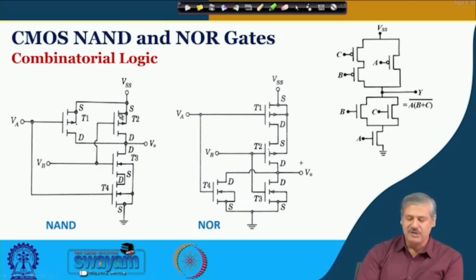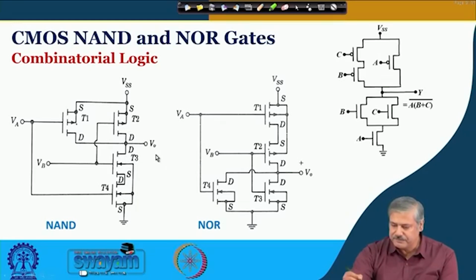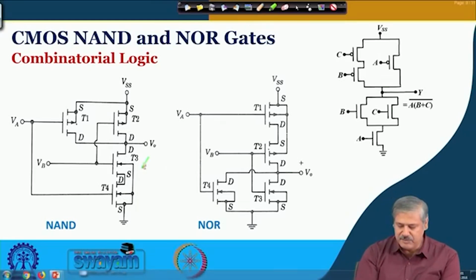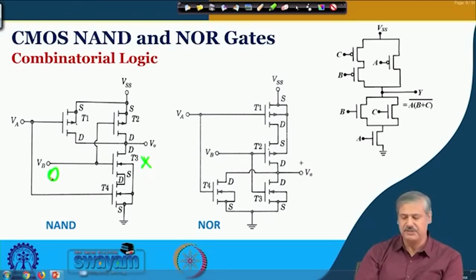Okay. So, any one of them is low. What is happening? Say VA is 0. So, this is in series, so this path will not be there. This path is blocked. So, this is blocked by this one, right? When say this is 0. Okay. But at that time, the corresponding VB, so this is 0 means this PMOS is on, right.